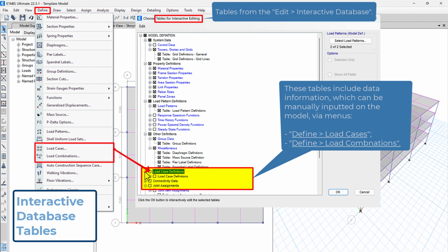The Load Case Definitions displays the tables related with the definition of the analysis cases currently available on the model. At the moment the program lists only two types of analysis, those being linear static, in use for the default self-weight or dead case, and a default modal analysis based on eigenvectors. When other types of analysis are added to the model, this list will expand to accommodate those.